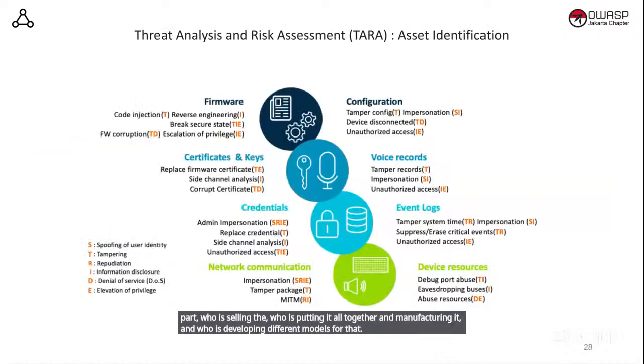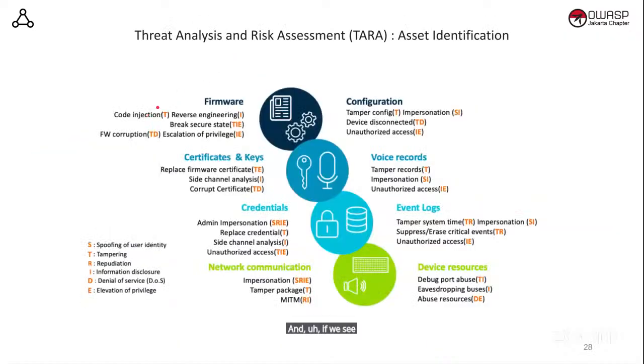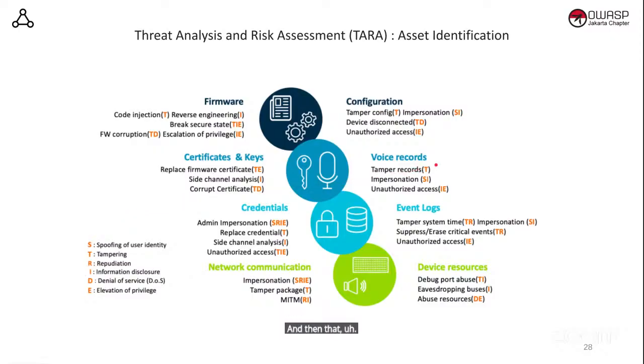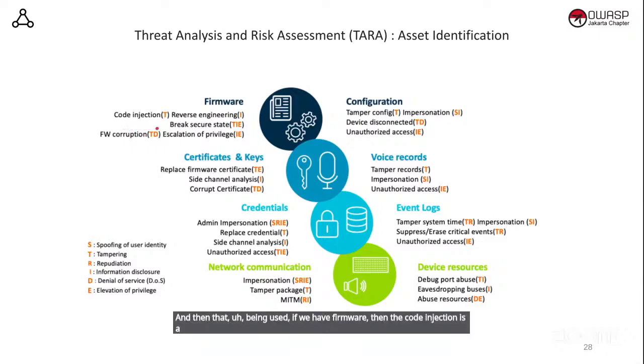And if we see, this is STRIDE, which is very famous for TARA, threat analysis and risk assessment. Then that being used, if we have firmware, then code injection is a threat. Tampering is a code injection. Reverse engineering is information disclosure, what particular logics they are using.